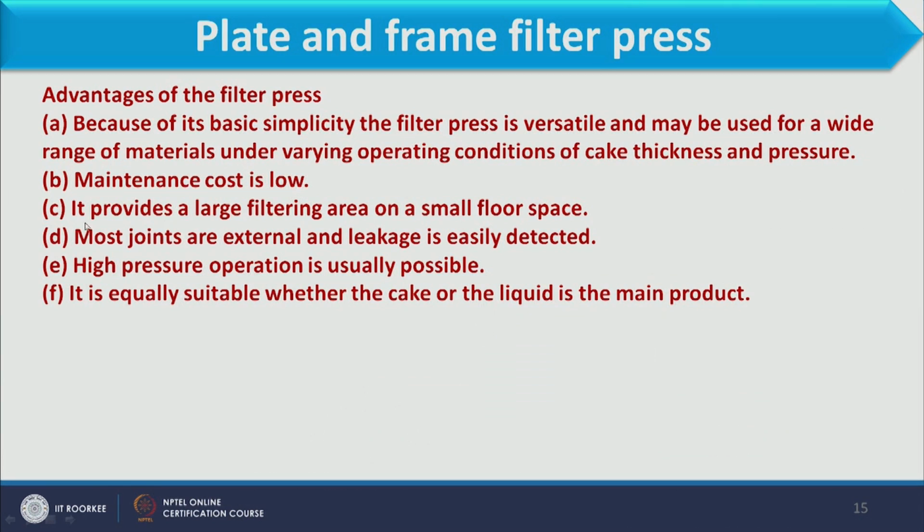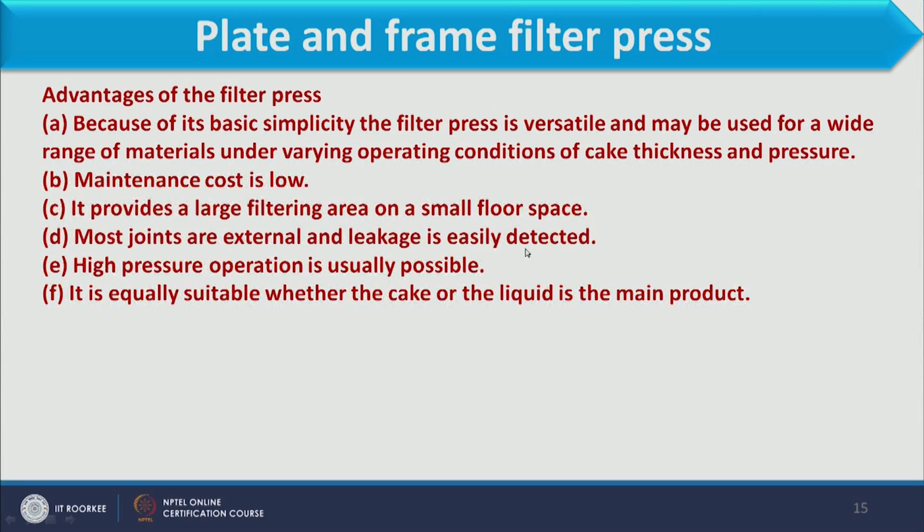Another advantage is that maintenance cost is low. It provides large filtering area on a small floor space, as I have shown you in the previous slide how large the size is, but because the filter media, frame and plate are all connected to each other, it looks very compact. Most joints are external and leakage is easily detected. High pressure operation is usually possible.